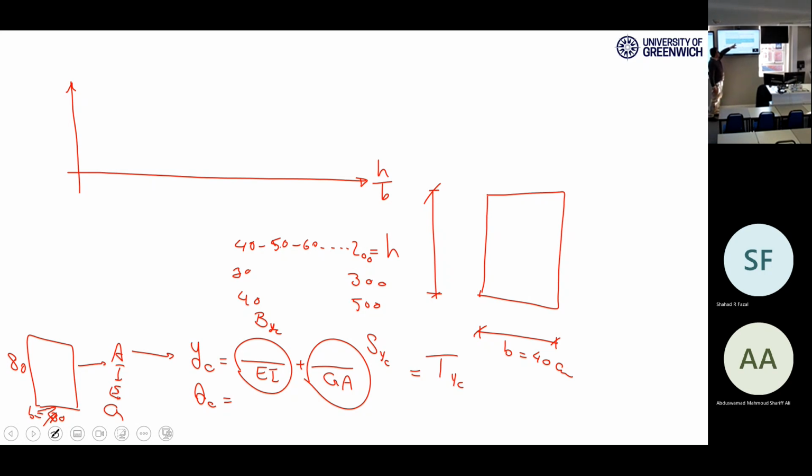See here, draw the ratio of shear deformation to the total deformation. The shear deformation means this one, and the total deformation means this one. This term divided by this. If you like, you can multiply it by 100 to get a percent. This is more beautiful, in terms of percent. How much percent is the contribution of shear force to the total deformation?